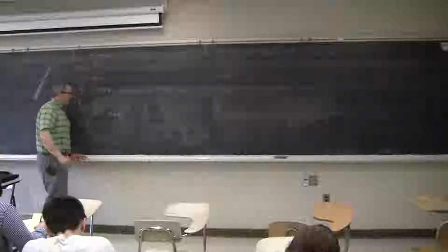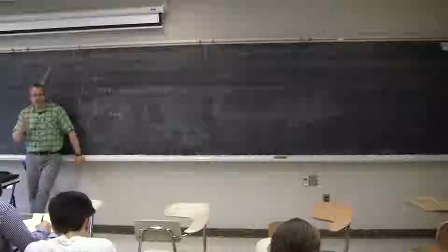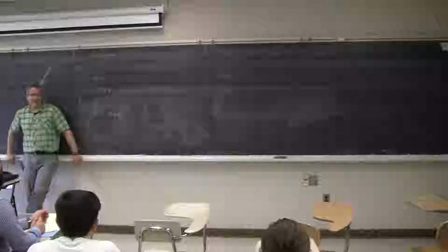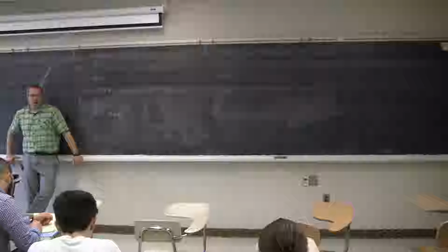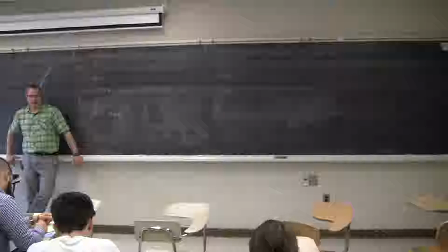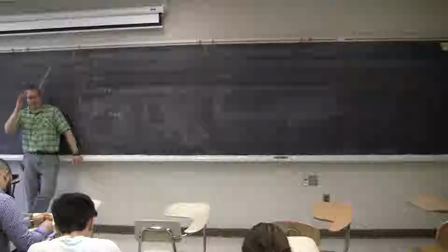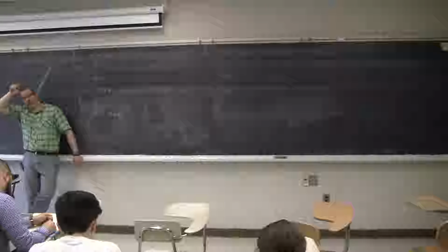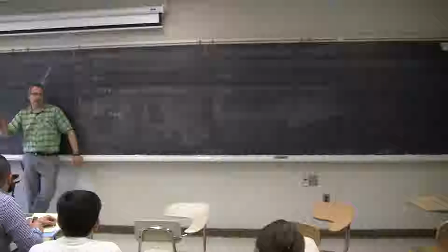So we didn't get too far into that because we kind of ran out of time. But DC machines are basically an AC machine that you just use a commutator to switch around. If you remember, the output of a DC machine kind of looked like a sine wave, but a little bit cockeyed. Well, how do you get an AC machine? Instead of having things perfectly lined up, you skew the slots a little bit. So instead of those hard or harder corners, you just tilt the machine so it smooths it out.